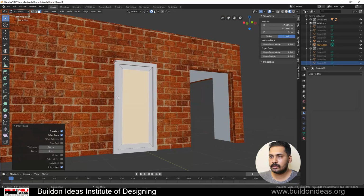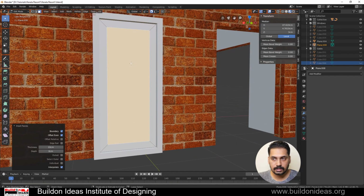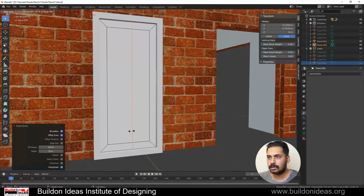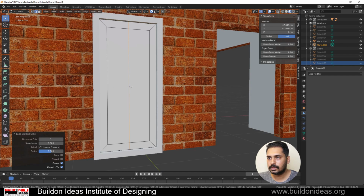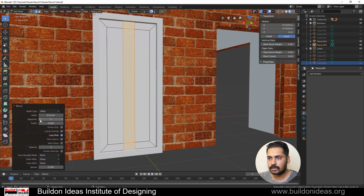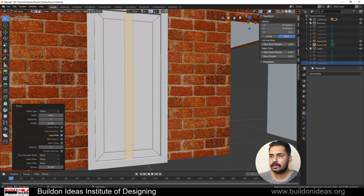You have the frame for the door, and then I'm dividing this by 1 like this, and splitting this by Bevel Edges. I just need 1 segment and 5, so that this becomes 10 centimeters.